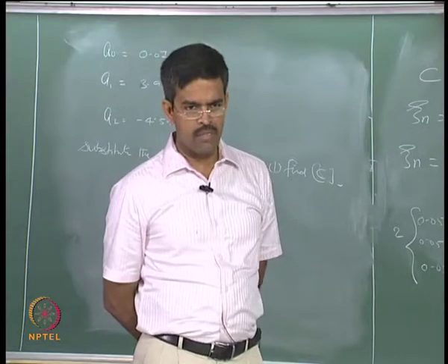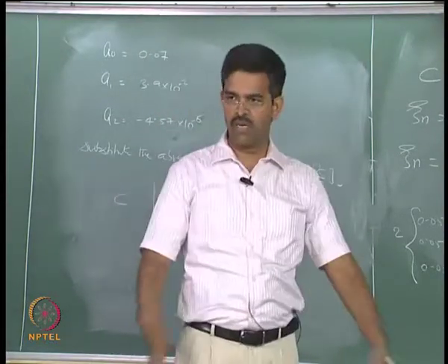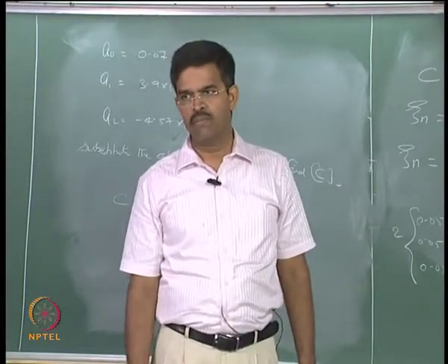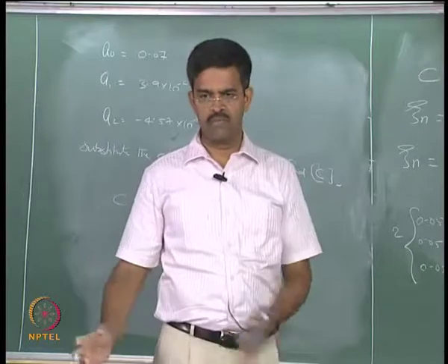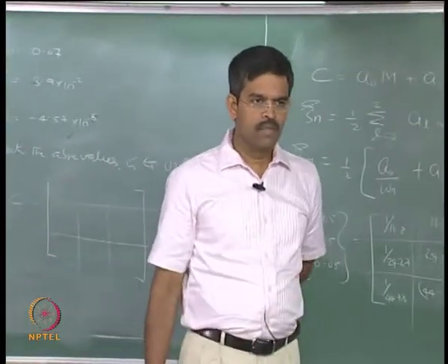In the Rayleigh's case we could not do this for more than 2 modes, now in Caughey's case it is general, we can do it for n minus 1 if n is the degrees of freedom. That is the deviation between this particular method and that of Rayleigh.